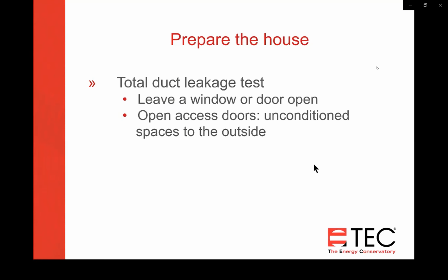We want to open those to the outside. So I talked about a well-vented attic or a well-vented crawl space. If there's any doors between the crawl space and the outside, you want to open those up. And same with any unconditioned spaces, you want to open those to the outside as much as you can, so the whole ductwork is seeing that 25 pascals of pressure. And for the test to be repeatable, you'll need to know what that condition is and how you set it up.